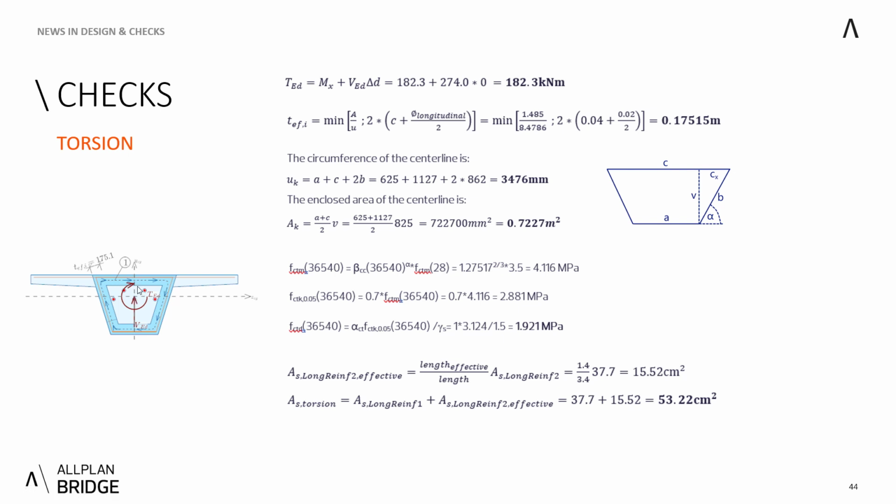And if the section is not loaded in the center of the shear, then you need to introduce an additional torsional moment. But in this case, the direction of the shear force is going through the center of the shear. Therefore, there is no lever arm, which we describe as delta T. Therefore, there is no additional increment, which can happen in a non-symmetrical section loaded, usually in some biaxial bending.